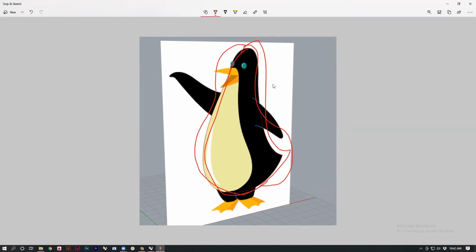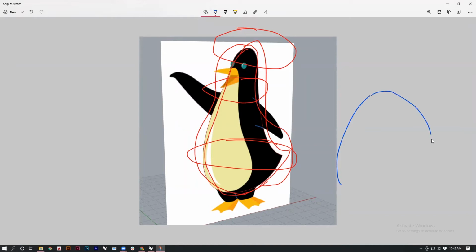Once I have this, I can also specify some circles at intermediate levels, and these will form the exact volume that we require for our entire object. Now, one thing I need to make sure of is at junctions such as these. At a junction where you have more than one or two curves meeting, I will have the two curves that I've drawn right now, and I'll also have two more curves in the other direction. I need to make sure that all of these curves meet at a singular point. If they don't meet at a singular point, we'll see what the problem with that will be. But for now, let's start off with all of these points meeting each other.